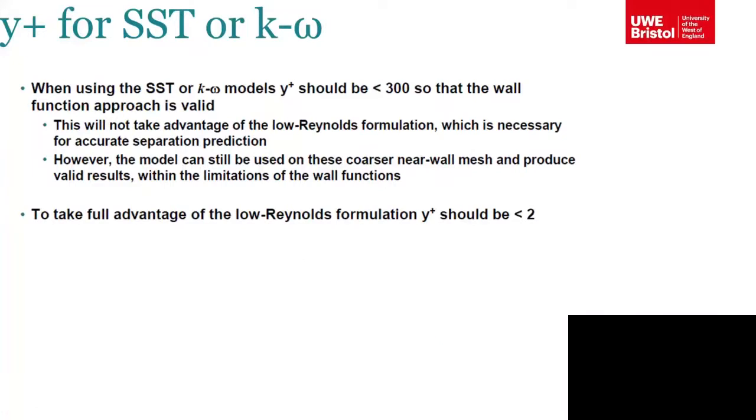Do we need to find y plus in our report? Not exactly, no. We're only using the K epsilon model. But use a boundary layer. You need to resolve the boundary layer to get a good answer.